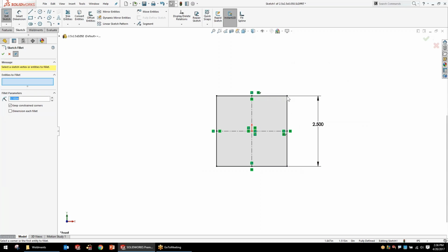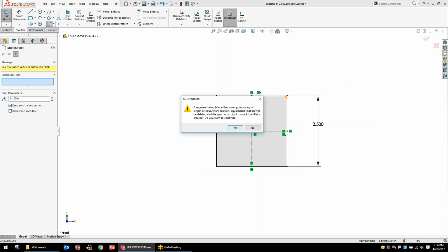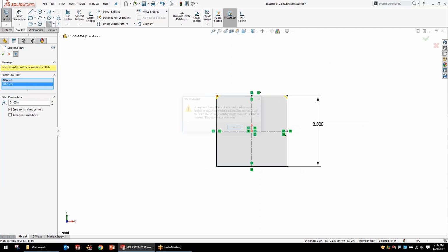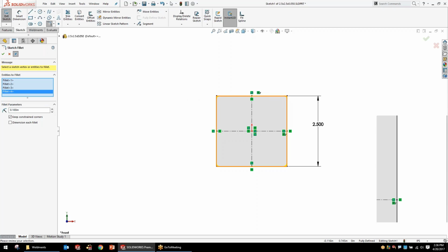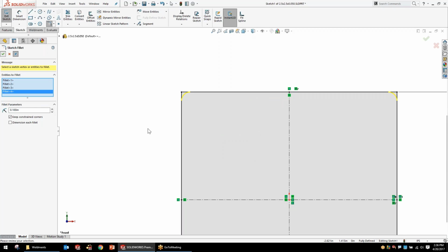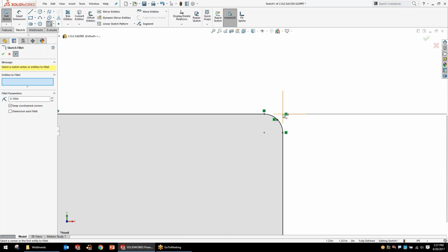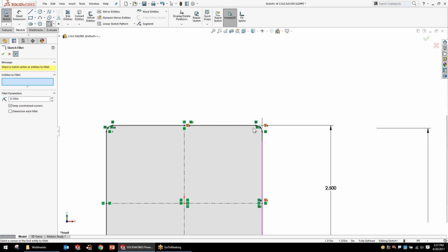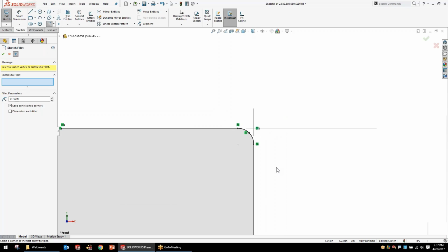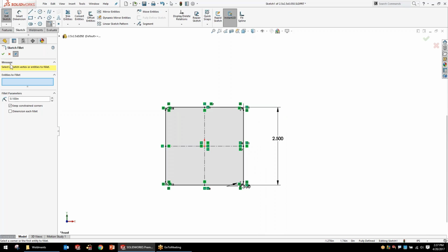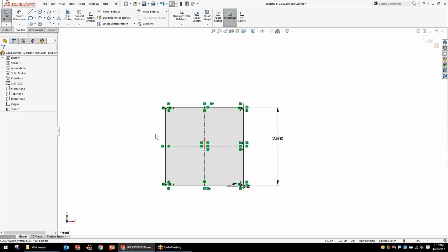Let's round the corners like it would be in the real world. It's popping up a message basically saying, hey, you're referencing lengths off of these corners, but you're trimming the corner to put a fillet on. So it has to create a virtual sharp. And a virtual sharp is here. You see that it imagines where the lines still extend to each other and intersect. And this dimension needs that virtual sharp to be able to tell what it's referencing. But that little message is not breaking anything when it pops up.